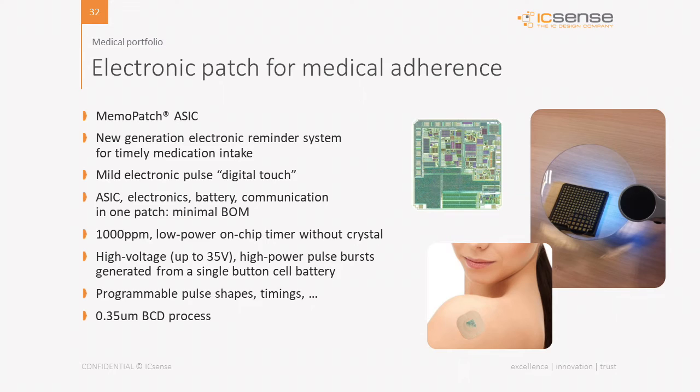Another example in the field is the electronic patch that we have developed for medical adherence. This is a patch that will give signals to remind you when to take your medicine, for example. The nice thing about this patch is that the ASIC, or the chip itself, integrated a lot of system-on-chip functionality. In that way, we could lower the bill of material of the whole system. Also, the chip had a very accurate on-chip timer without the use of a crystal. Also, sufficient programmability was requested by the customer.